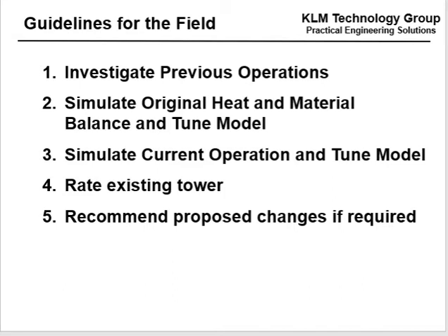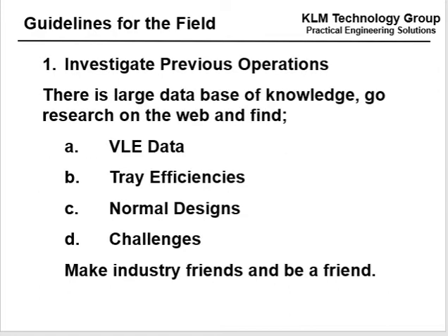Guidelines for the field. Investigate previous operations. Simulate the original heat and material balance and tune the model. Simulate the current operation and tune the model. Rate the existing tower. Look at the hydraulics. Recommend proposed changes if required. Investigate previous operations. There's a huge database of knowledge.